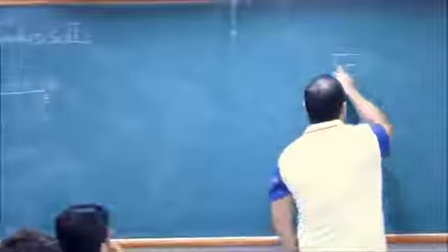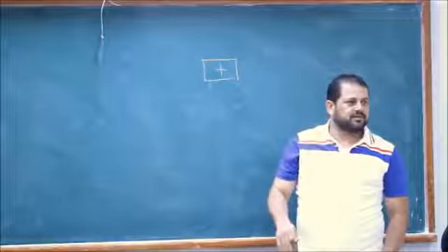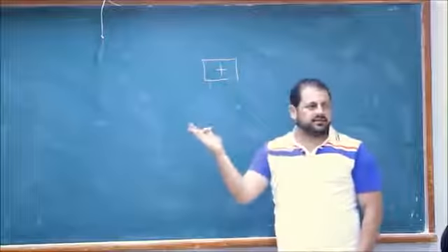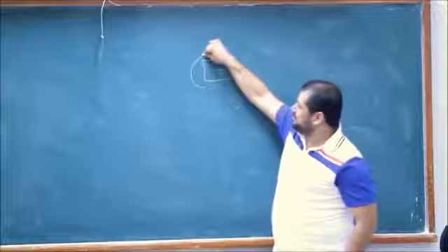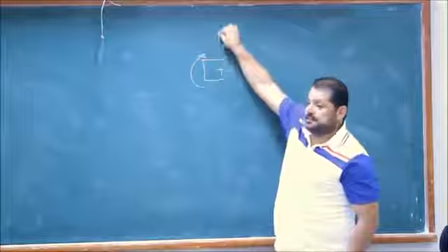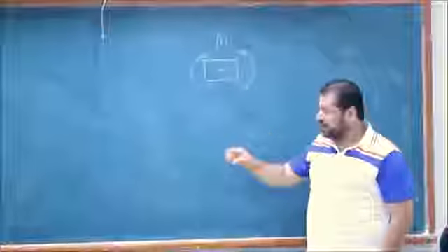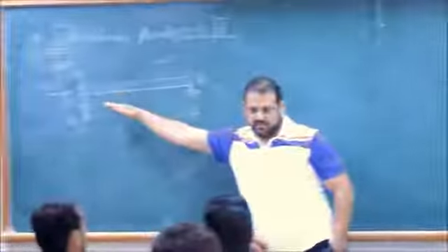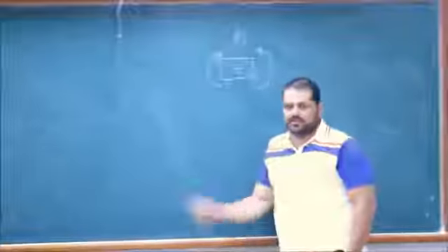What's the sign convention for the moment? Someone will say counterclockwise. Wrong. You tell me, it depends. Do you want it at the left-hand side or at the right-hand side? That's a positive moment. That's what I'm saying. When you draw the moment diagram, this is what your reference is. This has nothing to do with it. I will explain as I solve examples.